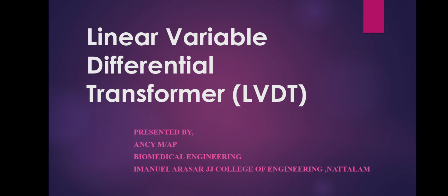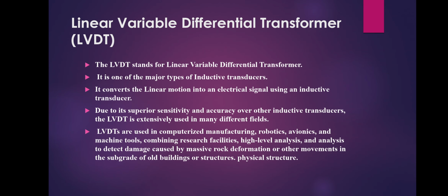Today we are going to discuss LVDT. LVDT stands for Linear Variable Differential Transformer. It is one of the major types of inductive transducers. It converts linear motion into an electrical signal using an inductive transducer.